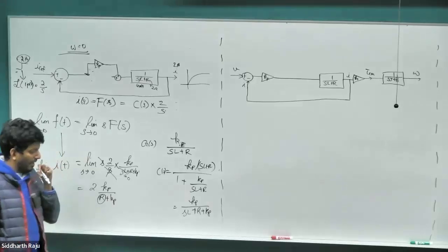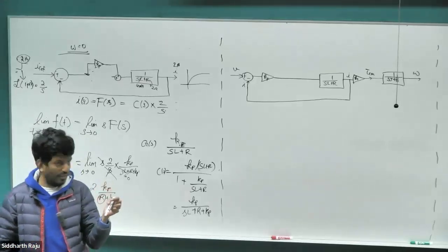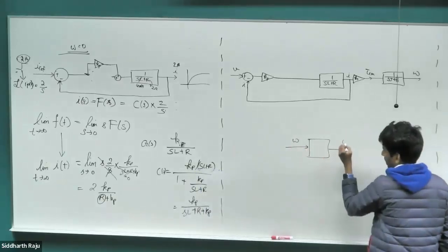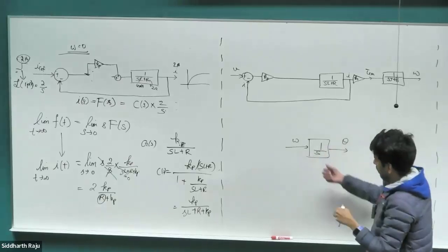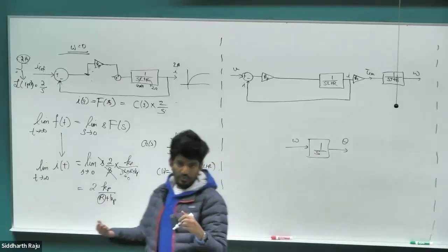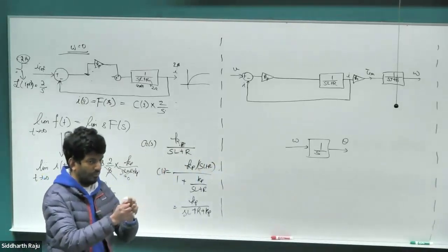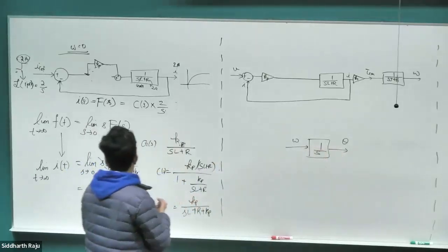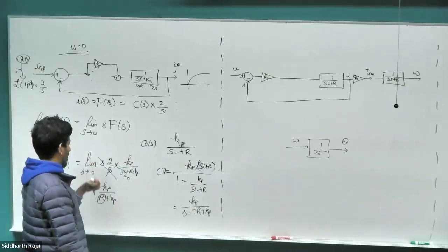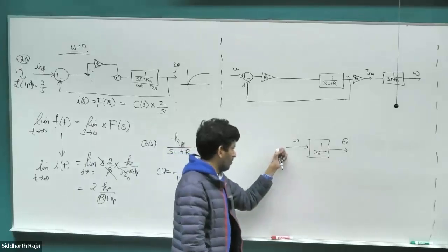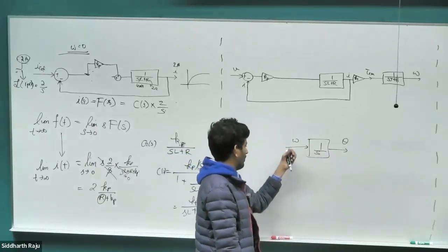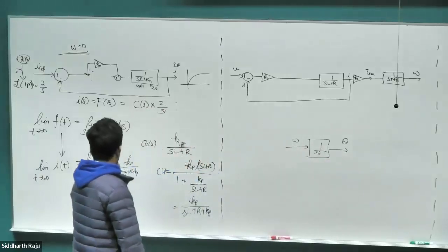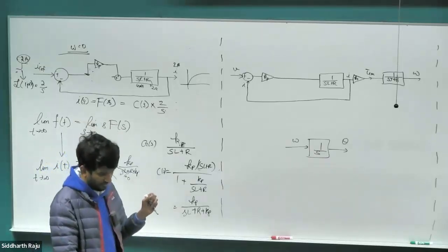That's why when you design your position loop controller, the transfer function from mechanical speed omega to your theta was just 1 by s. There was no plus some loss term to it. But if you had some kind of gear mechanism that can't hold the position in place, and it keeps slipping, that would be modeled as a loss term in the angle, which will then cause a decay and not reach steady state without an integral term. There you would add an integral term. But for an ideal system, where omega directly goes to theta, with no gear mechanism deteriorating it, you don't need an integral controller, as long as there is no external disturbance. So this is what you would want to answer for that question.